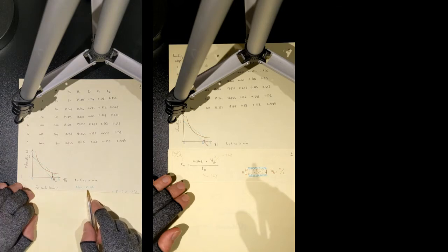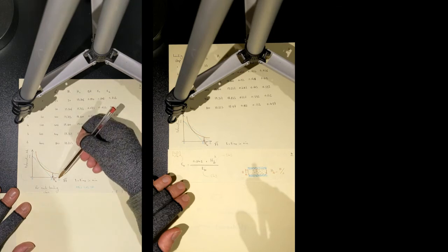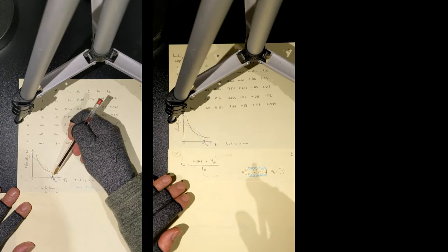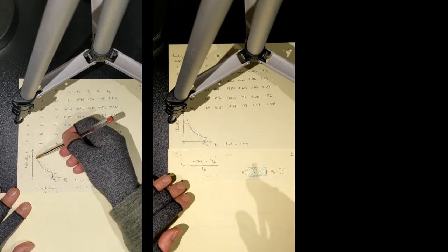Why 1.15? It's an empirical number, and it's a convention. Let's put it that way. So you found a second point on the horizontal axis. If you now connect this second point on the horizontal axis with the point of intersection on the vertical axis with a dashed line, your dashed line will intersect your data curve in 2 points. Forget about the first point, look into the second point.